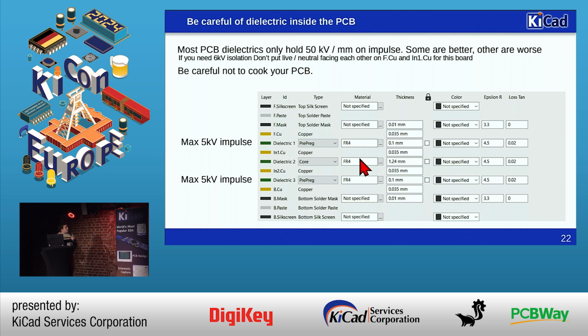So in this instance, if I have only 0.1 millimeter, maybe we should not have 6 kilovolts across this dielectric. So we should not put live and neutral here facing each other if we have a 6 kilovolt requirement.